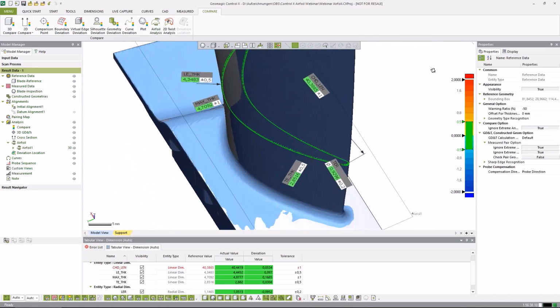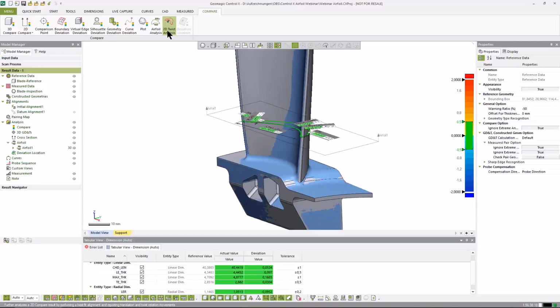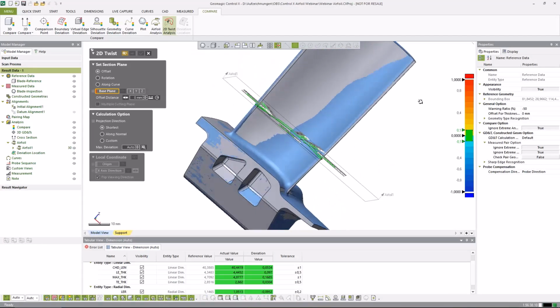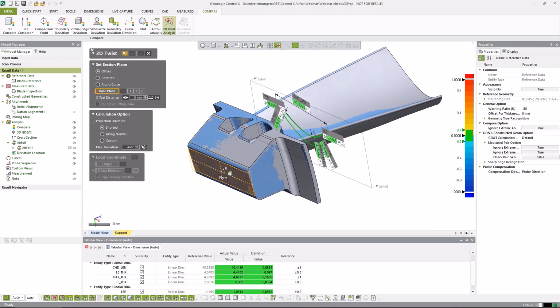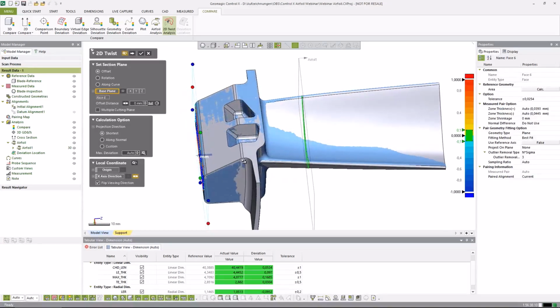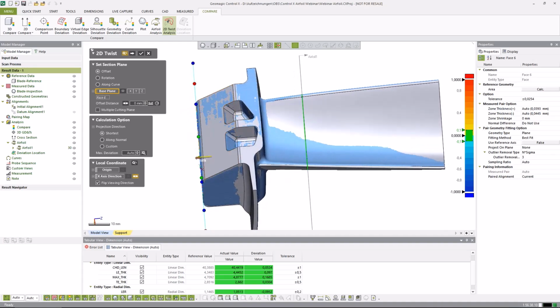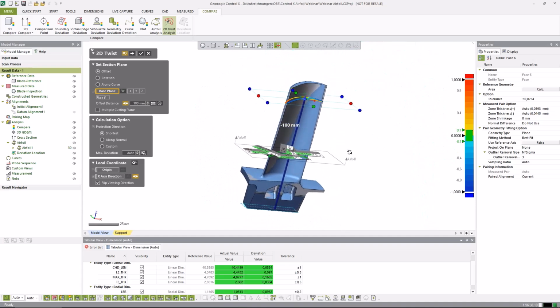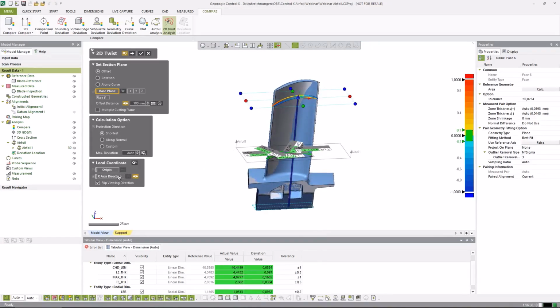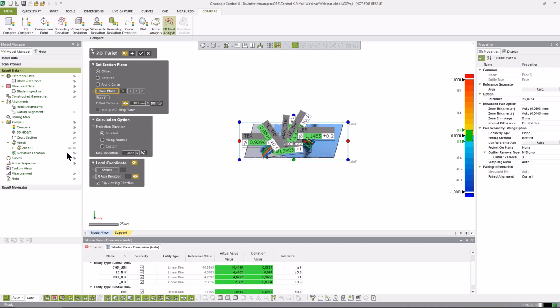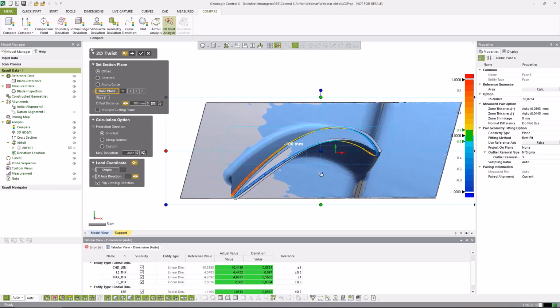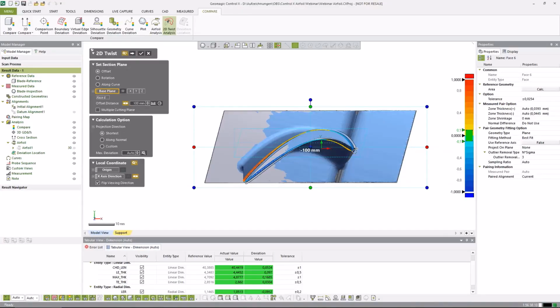So this is the airfoil analysis, and we have the 2D twist analysis. It's basically the same as a 2D analysis, just with a little twist. In this case, we can select the plane, the base plane as well. And I'm pulling up the section to 100 millimeter this time. As well, we can check the viewing direction so that we have the same. Disable this airfoil so that we have the same viewing direction. Also, our leading edge is in the positive x-axis direction.